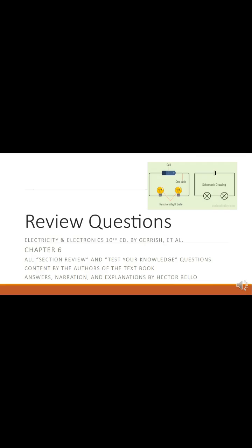Review questions, chapter 6. What does a voltage regulator do for the lights in an airfield lighting system? It keeps the voltage total as required to keep the same current in all lamps, thus the same level of brightness. How much voltage will be found across a good fuse?